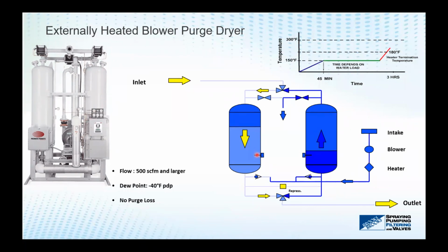So again, going back to what we talked about, lowering the temperature at the inlet of the dryer: for every 20 degrees that you lower the inlet temperature into this dryer, you cut the moisture load in half. So that's why Zenon and I are always banging the drum about lowering the inlet temperature, because it saves the end user a lot of money in regeneration costs.